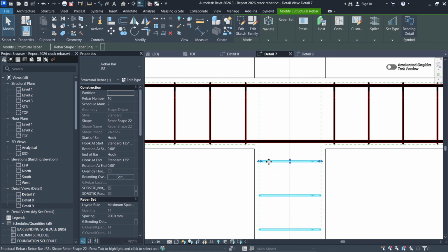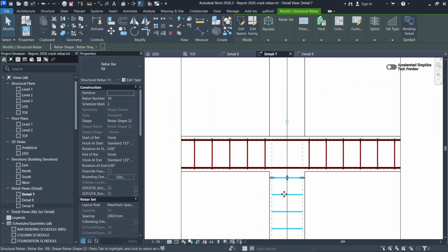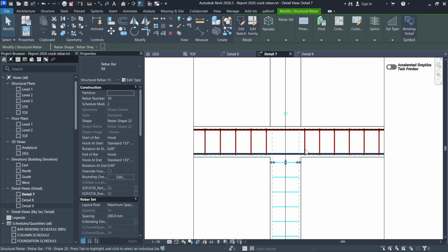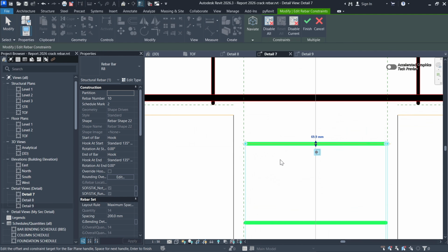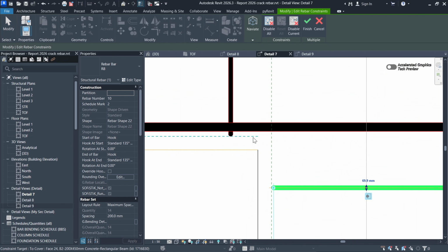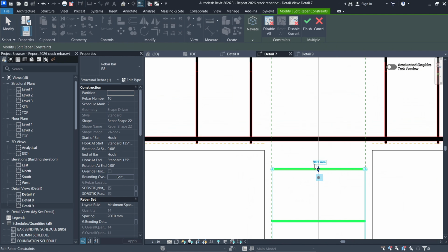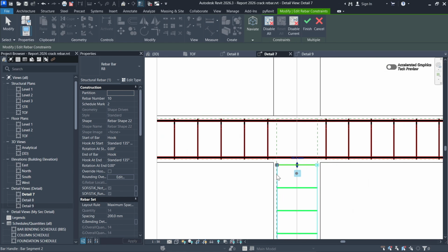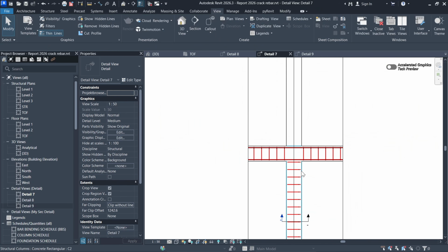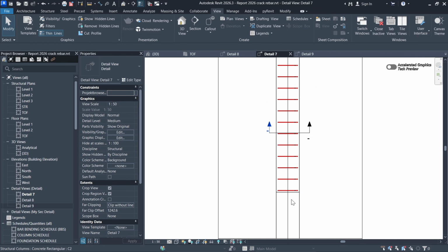Now I'll constrain it right here to the cover so that as I start propagating, it should behave well. All right, so I'll go to constraints and edit constraints. I'll pick the center for the stirrup and pick the cover. All right, so I'll pick the cover and let me just have 50 millimeters. Click outside and click on finish. So the bar is now constrained right there.